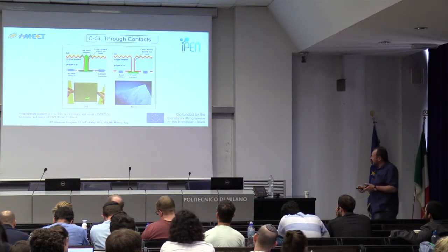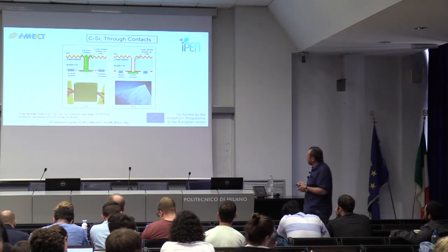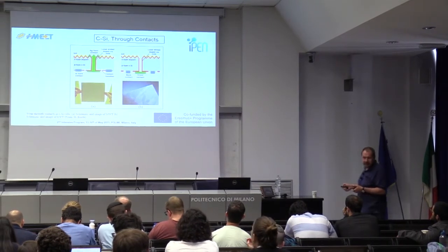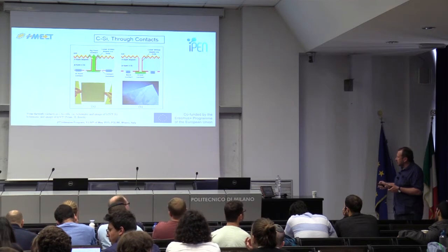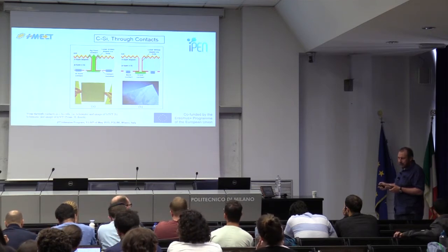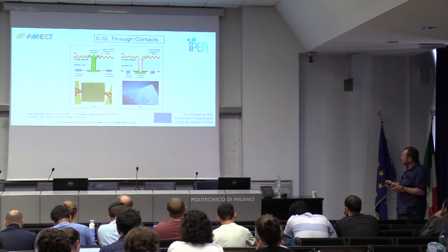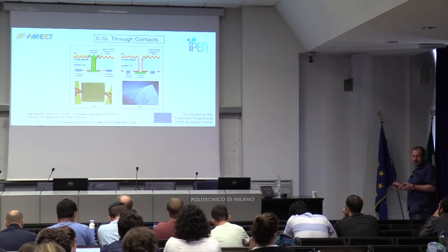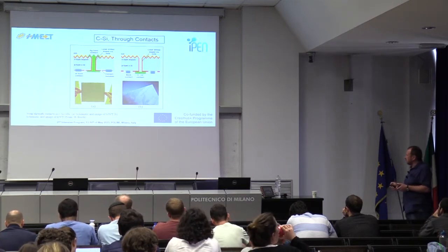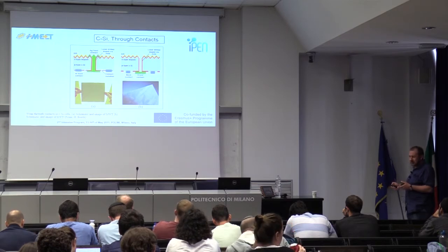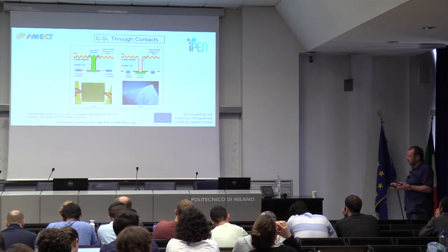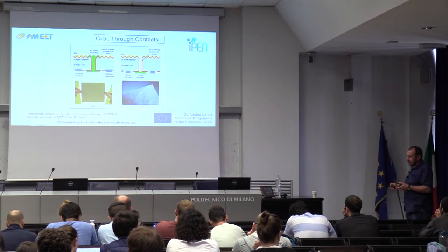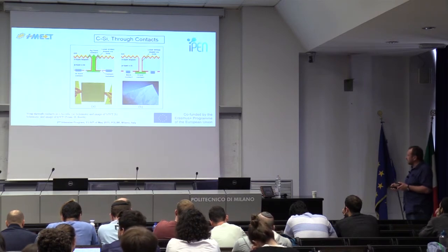This bottom left picture actually should show the holes. I'm not sure that they are well visible. You can fill the holes with metal and bring the top contact to the back of the silicon solar cell. Or if the inside wall is heavily n-doped, then it is also conductive, and you can just place the so-called top contact here on the bottom of the silicon cell. Of course, you also have to do some further structuring here, cutting or separating this highly conductive N-type layer.